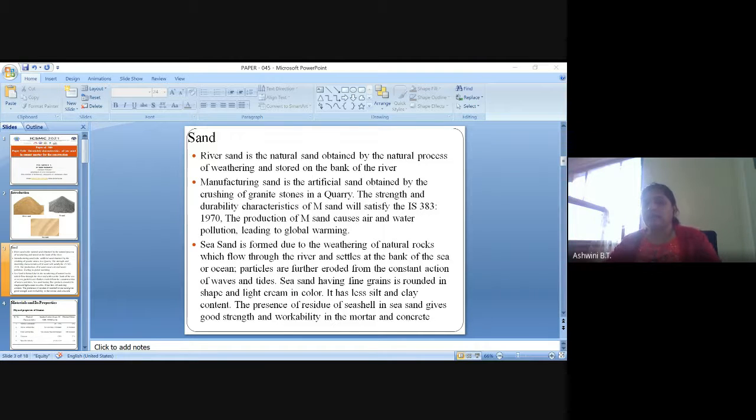So the methodology we have done for cement mortar 1:6, and we have prepared the sample according to IS 2250 1981. The workability of mortar is checked by using flow table test. It is referred from IS 14031, and the compressive strength of mortar cubes is done. Then the durability of mortar cubes, it is both, one is carbonation test according to IS 3466 and chloride test with respect to IS 14959 we have conducted.